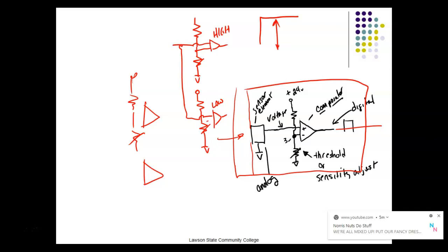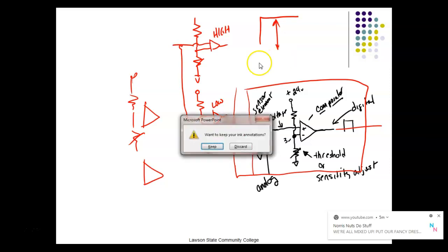Does that make sense? We'll go back in a minute and look at the ultrasonic sensor, and we'll see we've got 2 adjustments on it, so we can set when it trips on the high side and when it trips on the low side. What we're doing on the ultrasonic sensor is actually measuring the height of something. If it's got 2 adjustments, you can set what we call a span between what's true and what's false. If it's got 1, then all you can do is adjust the threshold.